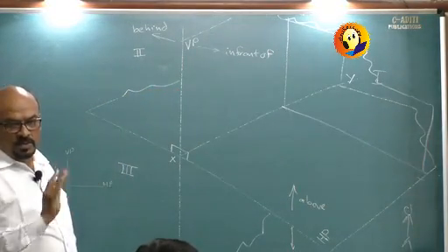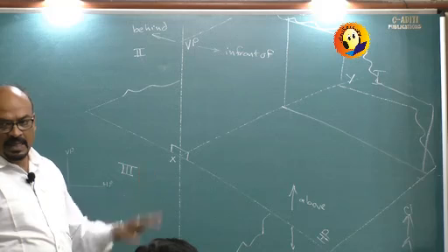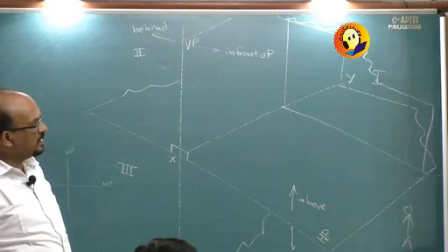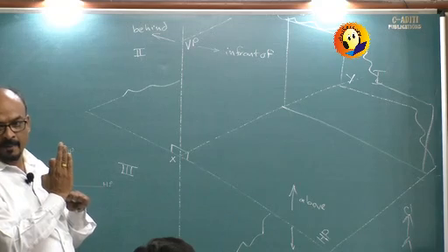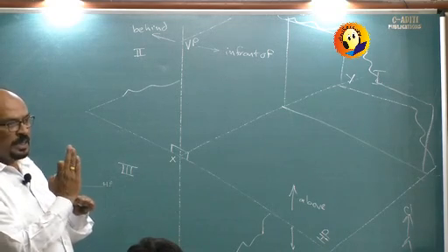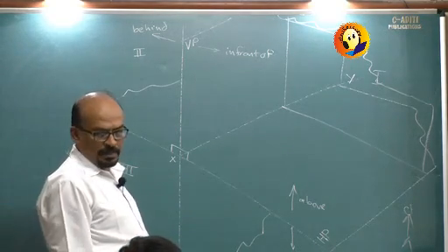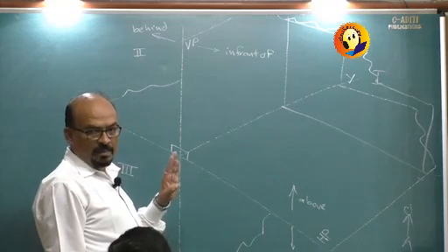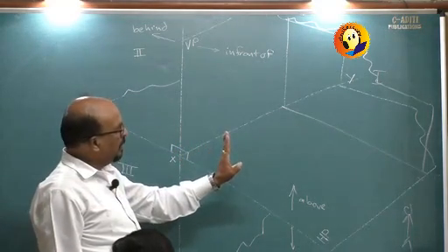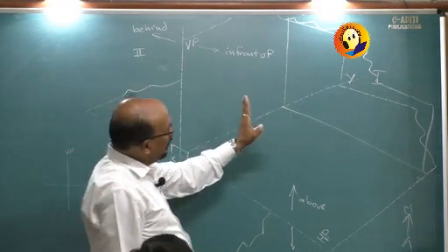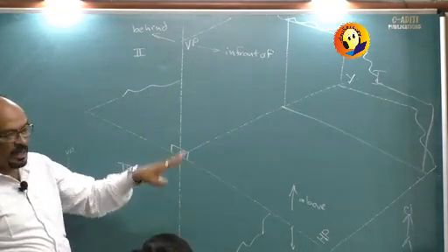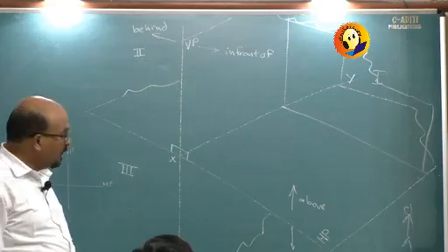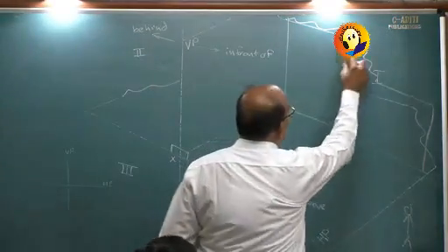But with reference to that, we don't say anything. We don't even name that. It is actually termed as the auxiliary vertical plane, because the plane is vertical. Okay, and it is auxiliary such that it is perpendicular to HP. Auxiliary vertical plane is normally perpendicular to HP. We also have the auxiliary inclined plane which will be making some angle with HP.